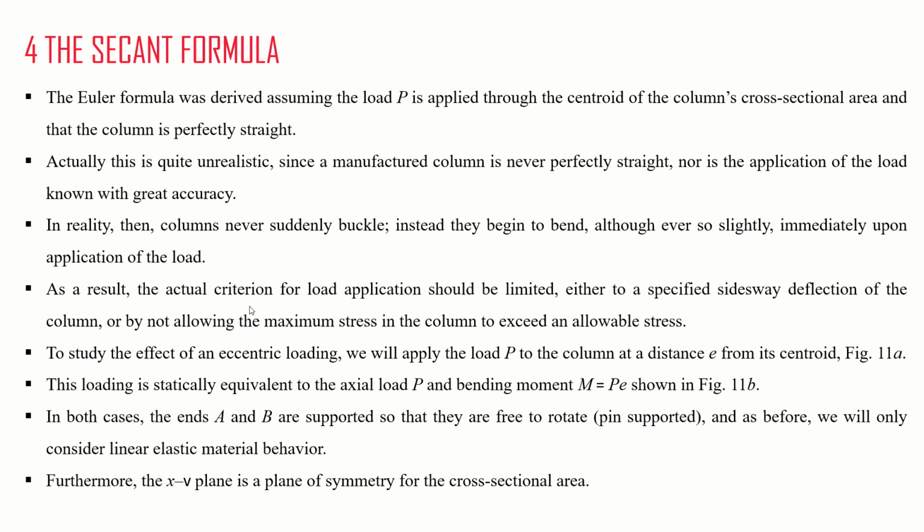As a result, the actual criterion for load application should be limited either to a specified sideway deflection of the column or by not allowing the maximum stress in the column to exceed an allowable stress. Now, what is this allowable stress? To study the effect of an eccentric loading, we will apply the load P to the column at a distance e, as I explained. This loading is statically equivalent to the axial load P and bending moment M equal to Pe. In both cases, A and B are supported so that they are free to rotate.